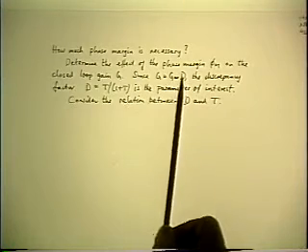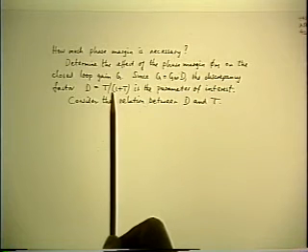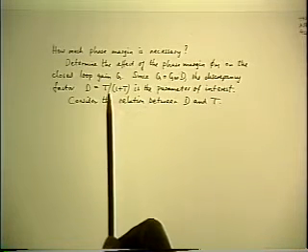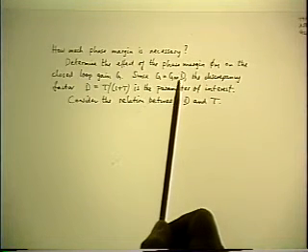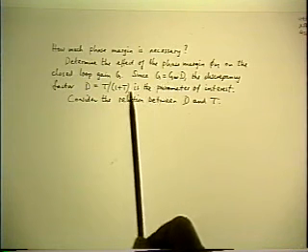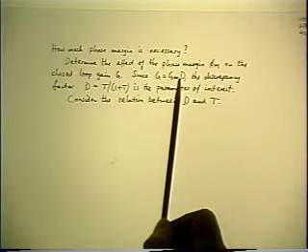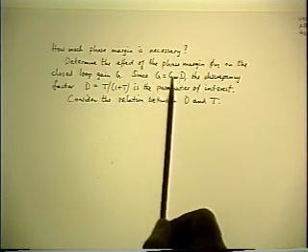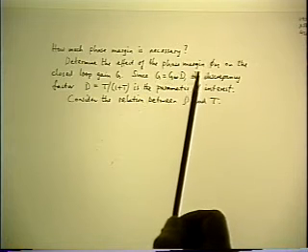The discrepancy factor is a unique function of T. The phase margin is a property of T. So the phase margin is inside the D as well. So there is something to do with the relationship between the phase margin and the shape of D, which is going to determine how closely the gain follows the specification.